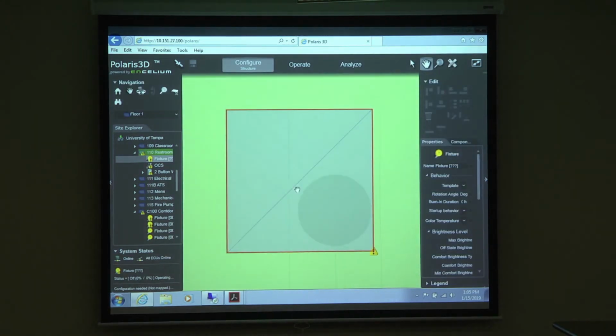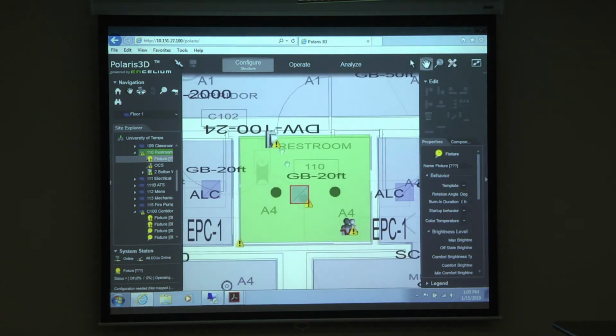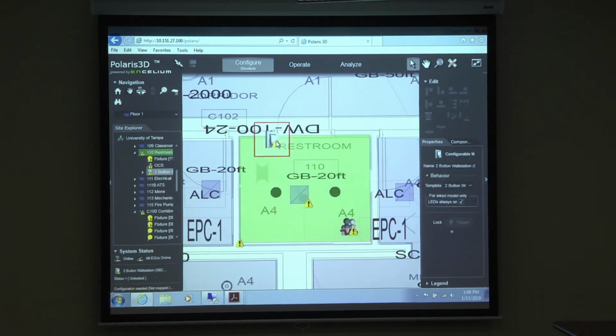Now zoom out a little bit, all the way out. Click on the pointer up top. You already have the module selected. Hold Control on your keyboard, and then click on the floor plan, the big room. Then click on the aux sensor in the corner there. That's a switch. Hold Control also. Click on the switch, then the aux sensor in the corner.